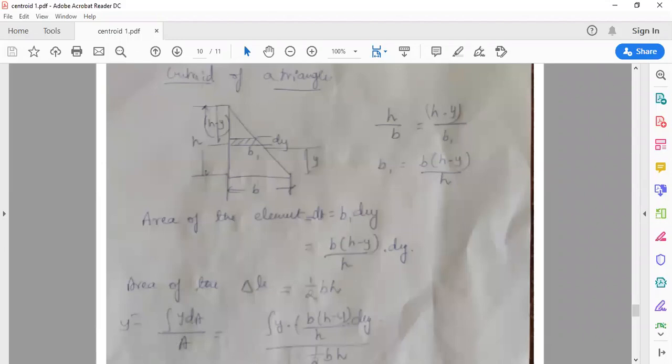In terms of integrals, we can write the integral of dA as capital A itself, and the integral of y dA is the first moment of area. We call it the distance multiplied by the small elemental area. This first moment of area, divided by the total area, is the centroidal location of any area. Y bar represents it with respect to the x-axis.